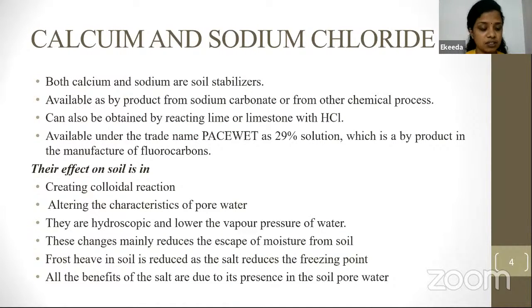So let's explain the effects in detail. First, this reaction is a colloidal reaction. They are hygroscopic and lower the vapor pressure of the water inside the voids of the soil particles. Water is present inside the pores of the soil particles, so when we add chemicals to the soil, it alters the property of the water inside the voids, and thereby we can get a better soil.